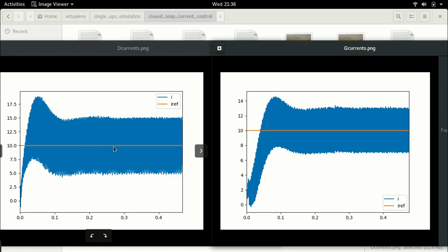The second thing is, since it is a PI controller, there is some amount of overshoot. You see here there's a hump. This hump is basically when there is an overshoot and it comes back down again. Now, by tuning your PI controller parameters, particularly by increasing Kp and adjusting Ki, you can reduce this hump such that it is perfectly tuned.